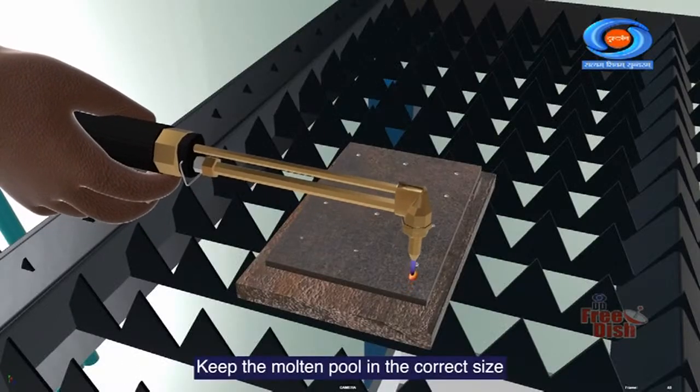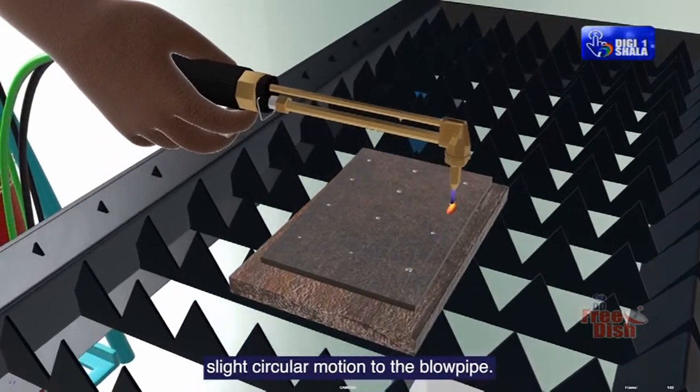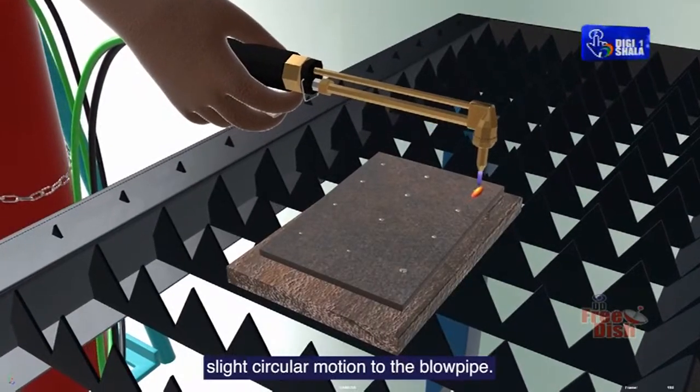Keep the molten pool in the correct size by adjusting the rate of travel and giving slight circular motion to the blowpipe.